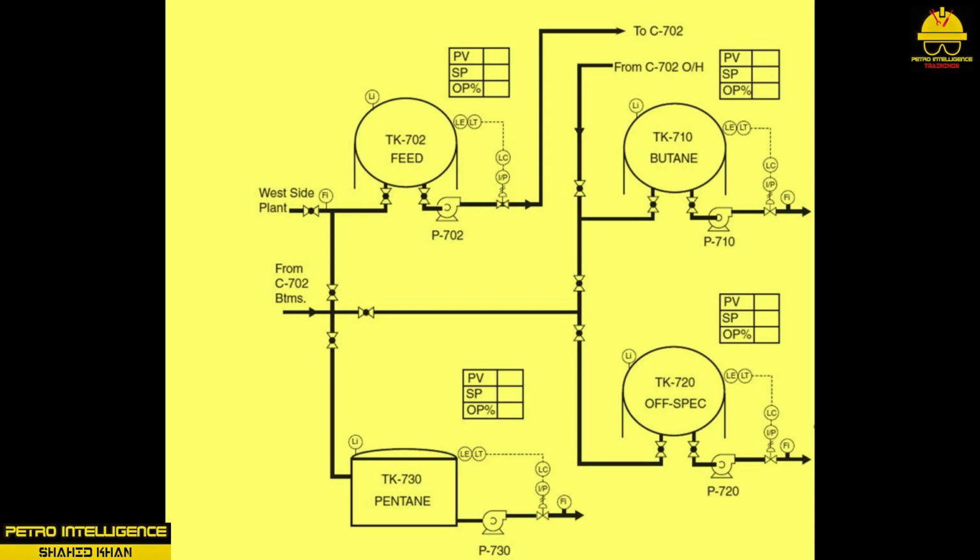Feed system. A collection of product storage tanks is often referred to as a tank farm. The tank farm has a complex system of piping, valves, and pumps that allow the technician to line up the various tanks in a number of arrangements. The tank farm in this example has 4 storage tanks assigned to the debutanizer distillation column, as shown in the picture. The primary feedstock used for this distillation process is a binary mixture of 37% butane and 63% pentane.